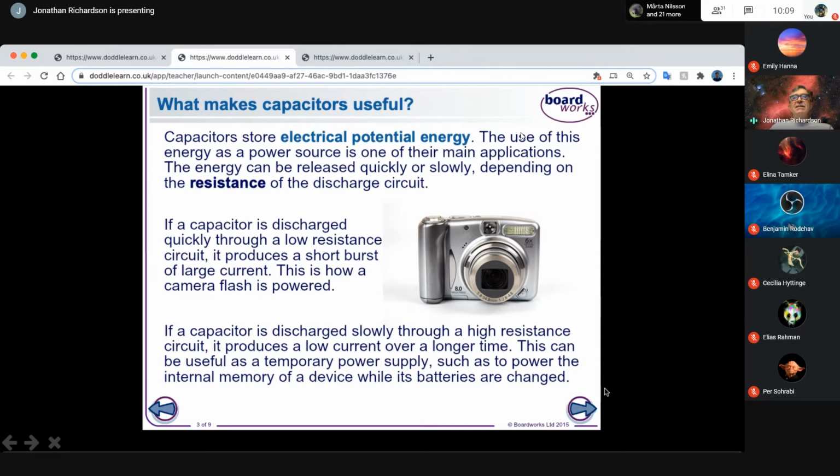And it sometimes says to you, please, once you've removed this battery, replace the battery within 5 minutes. The reason being, there is a capacitor which has stored the energy and is slowly discharging as it supplies the energy to the circuit. But after a period of time, the capacitor has completely discharged and it stops working.